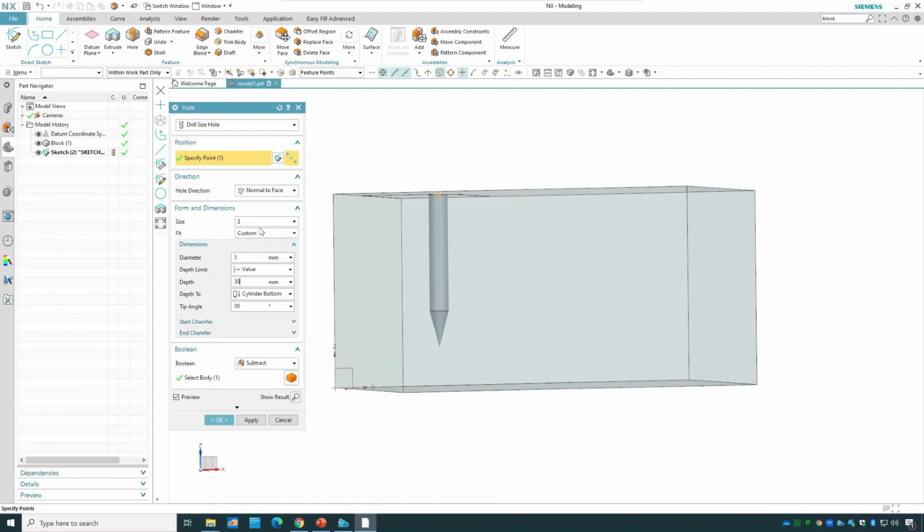Usually, if you work for small, medium-sized companies, they prefer to go with the standard version of the holes, or the drill bits, because it's cheaper to manufacture and is available on the market. However, if you work for the big companies, it's quite well known in the big German manufacturers, they prefer to have their own customized tooling sets. And there are a few reasons for this. First of all, you as a designer would have much more freedom to come up with your own design, so you're not limited to the standard tool sets.